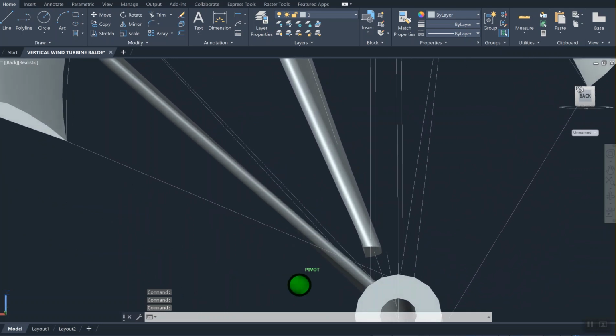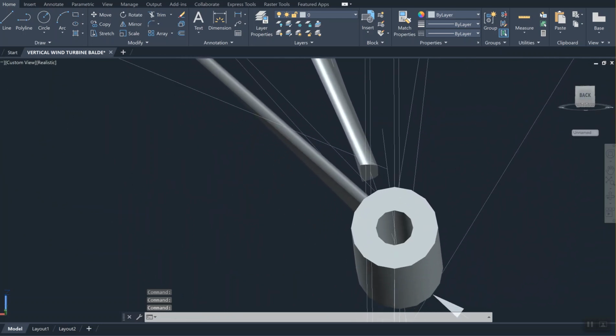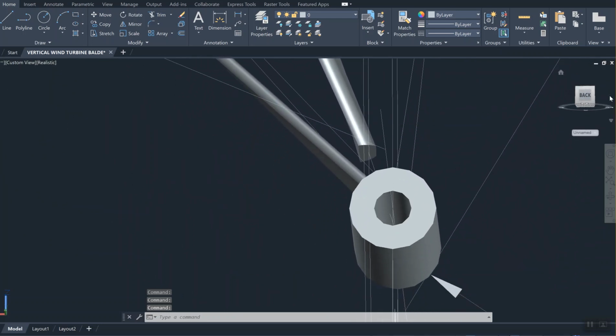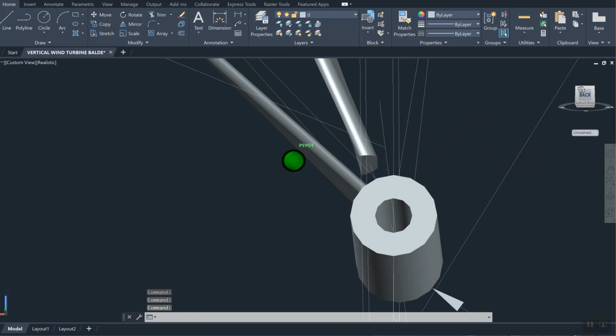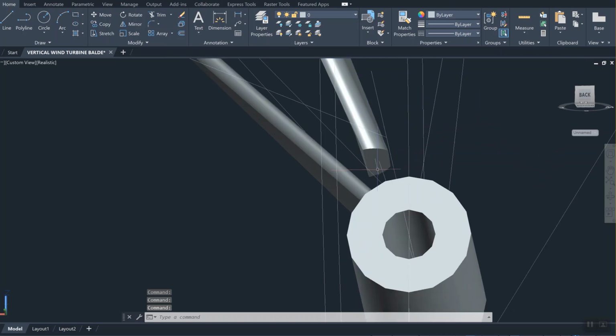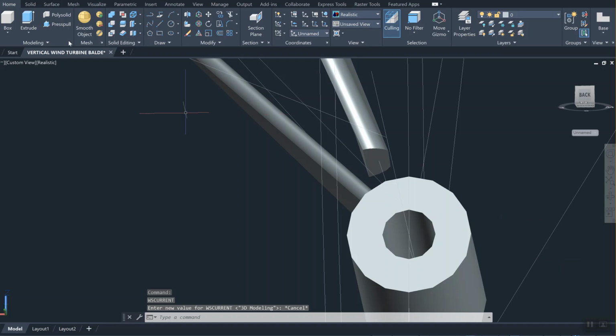So, for example, what can you do? I'm changing the angle from a view tool on the top. Okay, I'm going to extend this. Okay, so escape. And I want to change my menu to 3D menu. Go to 3D modeling. There's something called press pull. I wonder if I can press pull this surface. And it lets you press pull in a particular session.